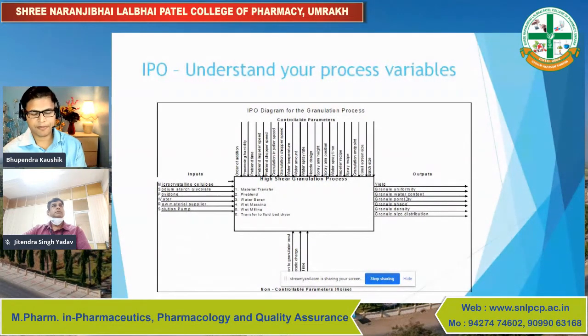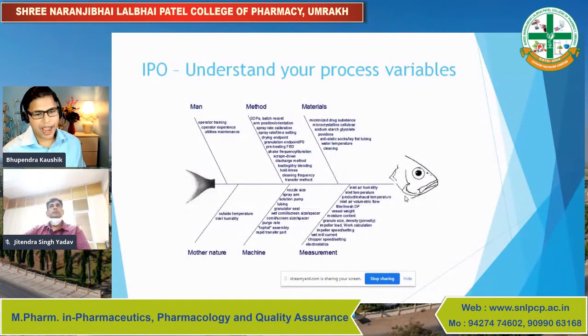This sort of study can be done using different tools. I have used IPO here, which is input, processing, and then output. But equally, you can use a Fishbone diagram, looking at the 5 Ms, and the 5 Ms are simply looking at where, for example, your variability may come from your manufacturing operator. Maybe the operator is not trained enough. Maybe the operator is trained, but that day he's distracted. Human factors. And maybe your procedure is not clear. Maybe the material you used during the processing of a particular batch was not of good quality.